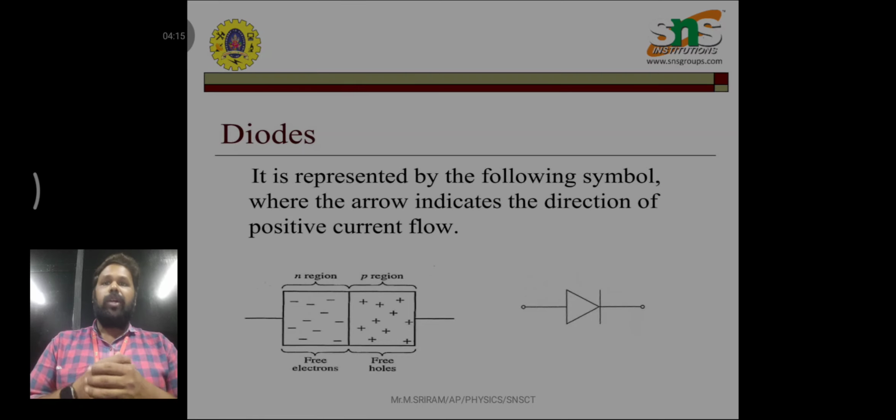And Zener diode. It is the most useful type of diode, and it can provide a stable reference voltage. These are operated in reverse bias and break down on arrival of a certain voltage, if the current passing through the resistor is limited. A stable voltage is generated. Zener diodes are widely used in power supplies to provide reference voltage.